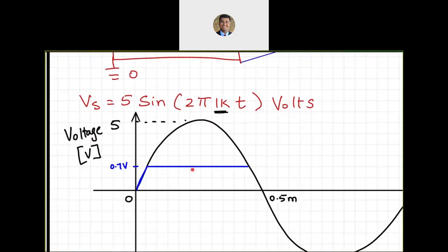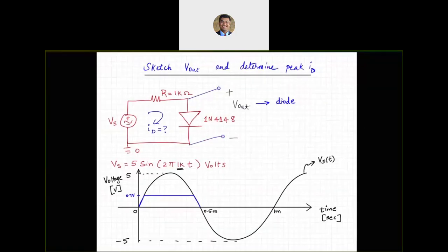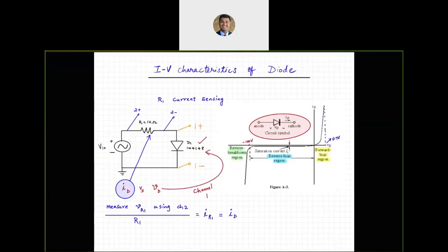Notice this is a theoretical exercise. In practice, that might look like a slight curve over there. Next, as I decrease it from 0.7 back to 0, it is going to follow the same way. And can I go negative? Absolutely I can. When I move to negative voltages across the diode, I can see those negative voltages.